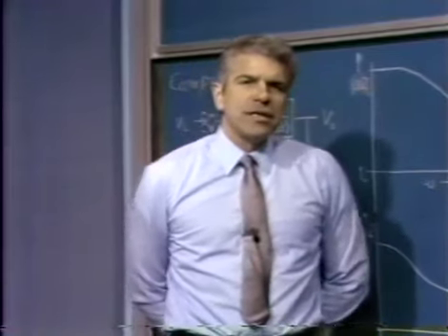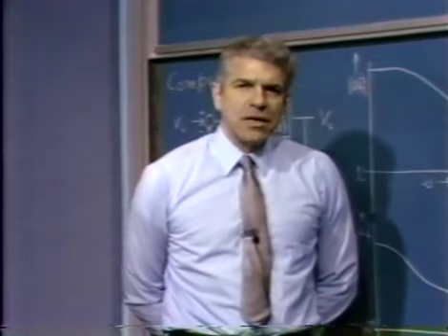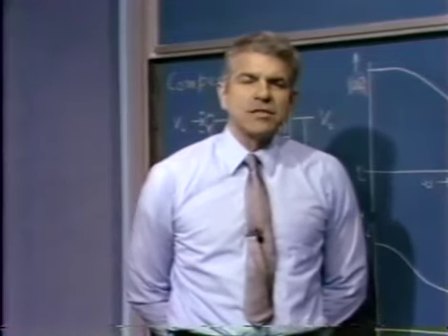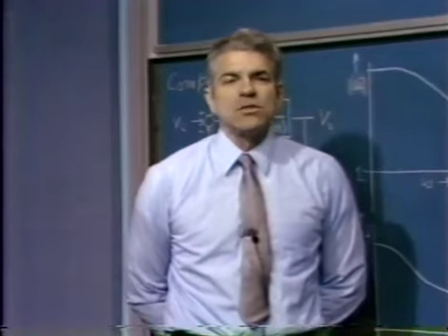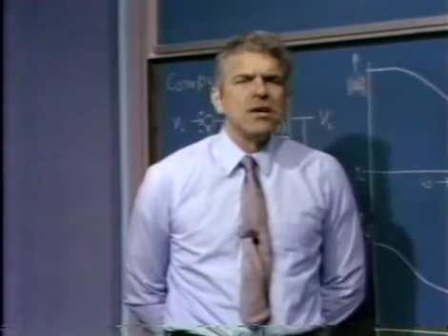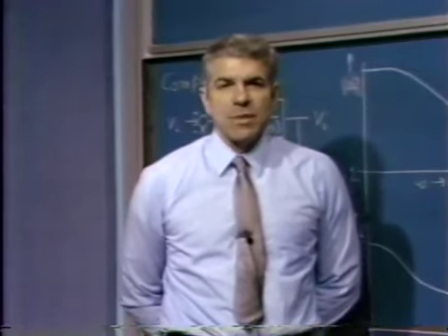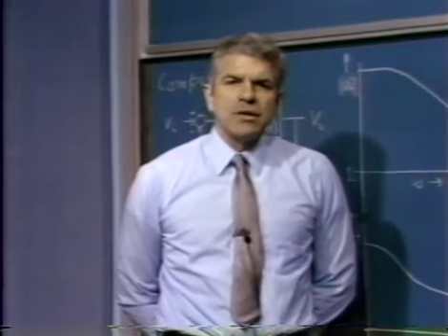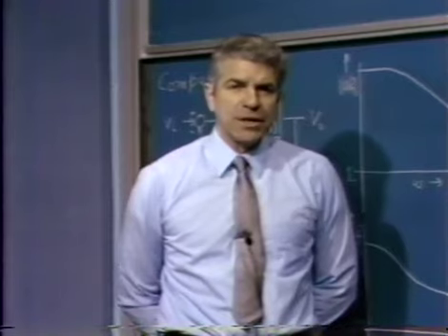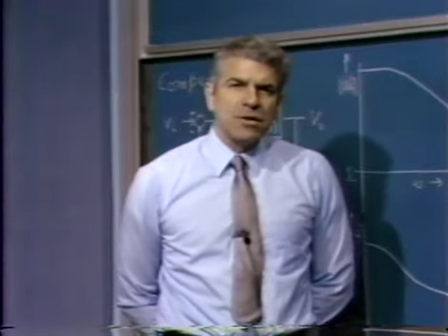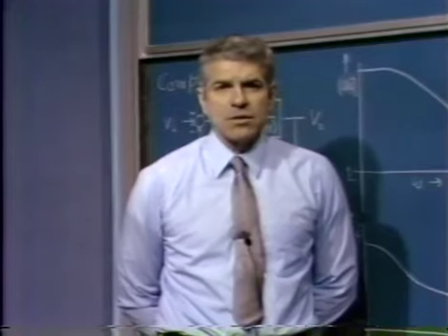Gain margin is kind of an override kind of a thing. Not much happens to deteriorate system performance until we get down to gain margins that become too small. And what's too small? Well, if you have a gain margin of 3 or more, possibly, or maybe a little bit more than that, it turns out that the gain margin has relatively little influence on the relative stability of the system.